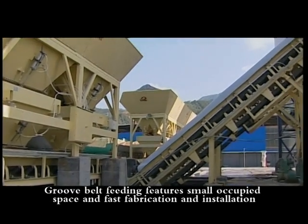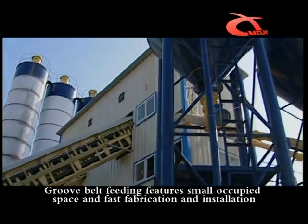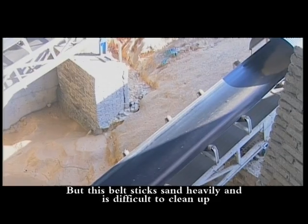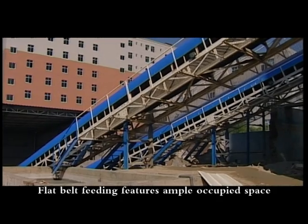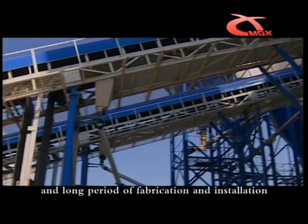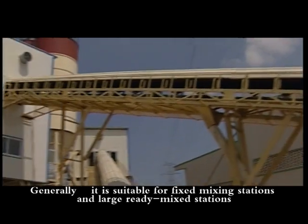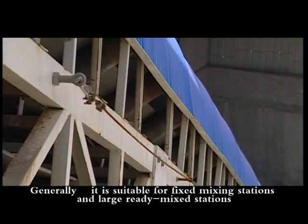The groove belt feeding system features small occupied space and fast fabrication and installation. However, this belt tends to get more sand stuck on it, and it's more difficult to clean up. The flat belt feeding requires ample space and a longer period of fabrication and installation. This belt has an automatic cleaning device. Generally, the flat belt is appropriate for fixed mixing stations and large ready-mixed stations.